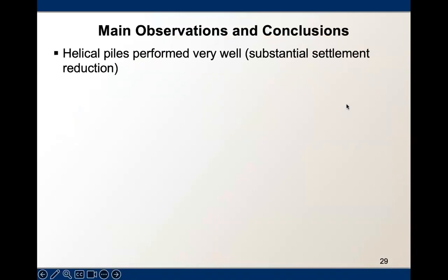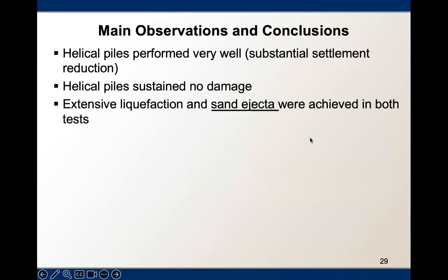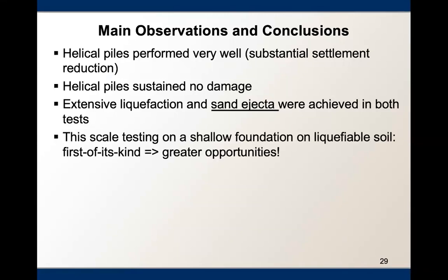So some of the key observations: overall, helical piles performed very well. They did not suffer any damage. We were able to reproduce sand ejecta in our test, which was really key. This large-scale testing on this phenomenon is really one of the first of its kind. So there are some great opportunities, and I'm going to talk briefly about that in a bit.